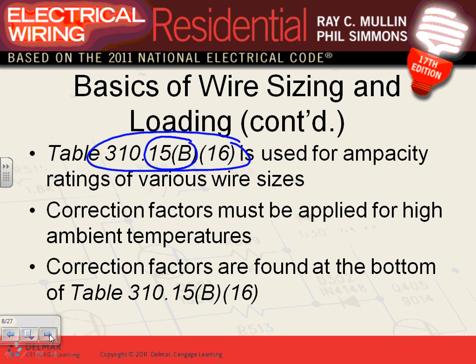I know you've seen it before in the first year and all this stuff, but I want to give you my 2 cents on how to use this table. Okay? I'm going to give you a couple of hints. What I gave you before, guys, all these conductor sizes that match the overprotection device, that's coming from 310.16. So be aware of that one.